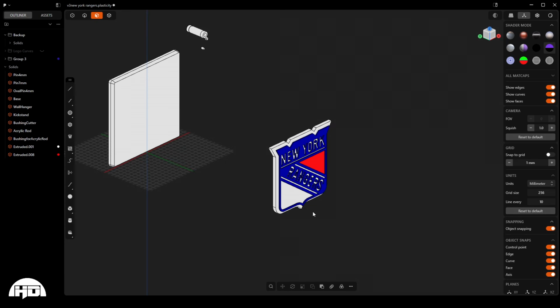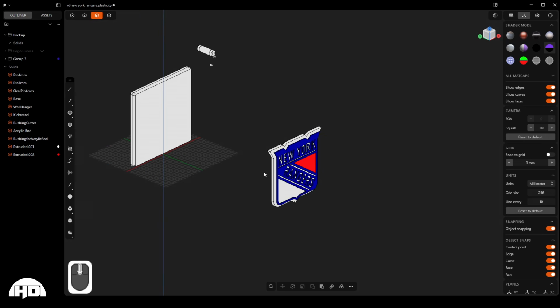It has tools that make adding repeat objects to other objects and booleans very, very quick, very easy, very efficient. And a boolean is basically where you're combining 2 pieces of solid geometry, or you're using one piece to cut out, basically the negative cavity, which we're going to do both right now, so you'll see.